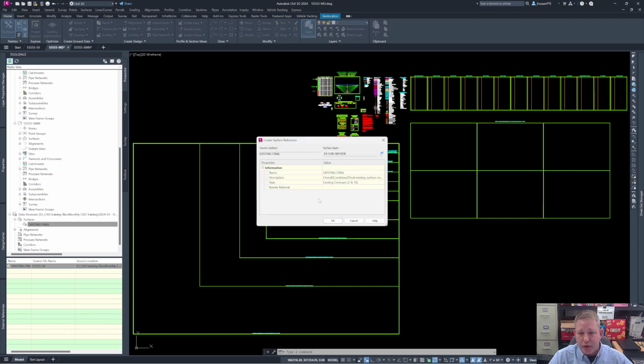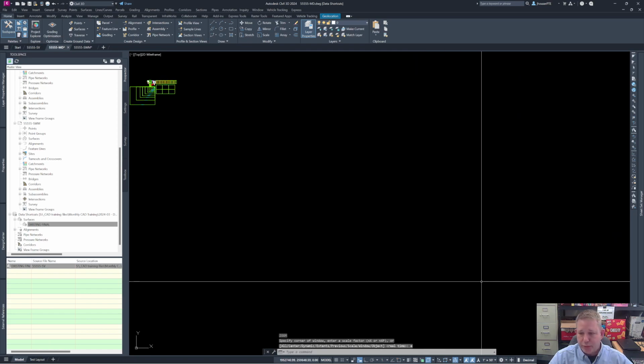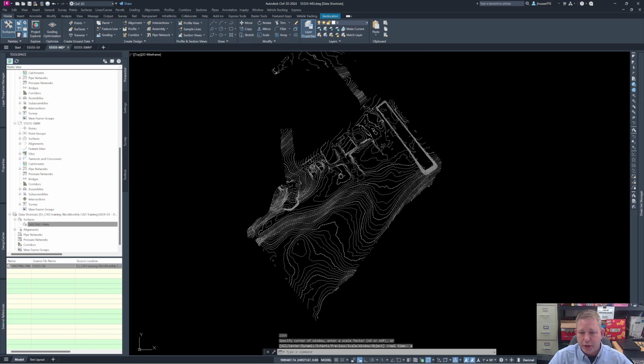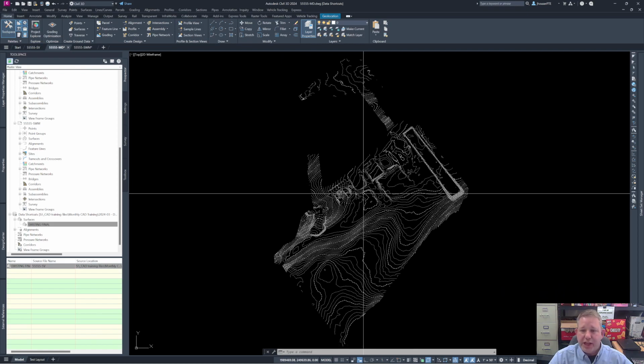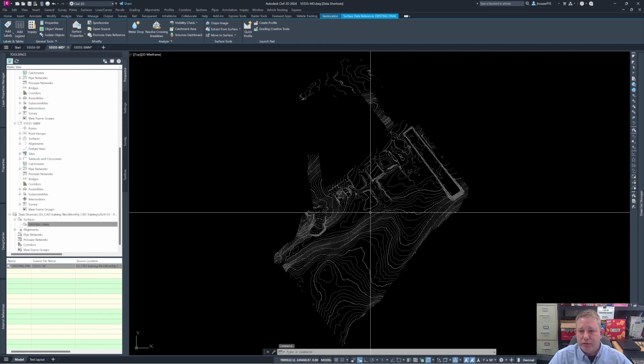You can also change how you want it to come in. So let's say, hey, we'll assign, actually, we'll go with the 1s and 5s existing conditions first. Nope, not proposed, existing. So once that is brought in, I'll zoom extents, pan on down, and now I have the same exact surface in the MD that was actually built in the survey drawing.